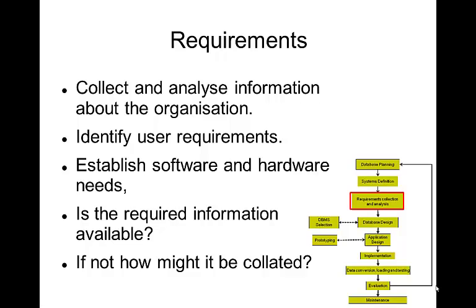And that is all very well, but then you're balancing the cost of collecting the data versus the benefits of having the data collected in the first place. So we were contracting out the data digitization, but we had to provide the instructions for the digitizing company as to how to get the data off the maps. Do they take the mains off the 1920s 1 to 500 maps, then add the stuff that isn't on there from the later maps? Or do you digitize the later maps and then perhaps use the 1 to 500 scale to improve the location of the mains in relation to things like curb lines to get actual good, correct distances?